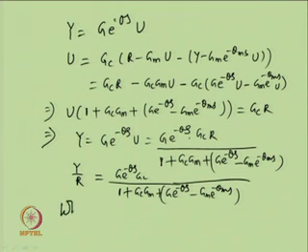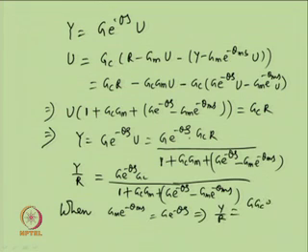Now, when the plant model accurately matches the dynamics of the actual plant, that means when G_m e^(-θ_m s) equal to G e^(-θs), y upon r becomes G G_C e^(-θs) upon 1 + G_C G_m. So, this is the beauty of the Smith predictor.